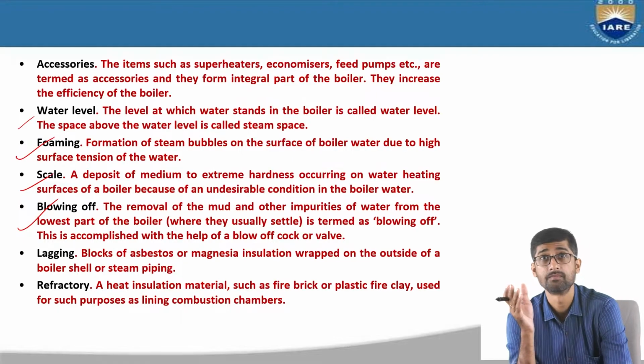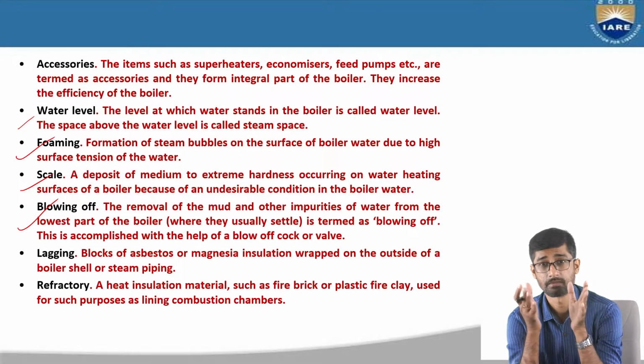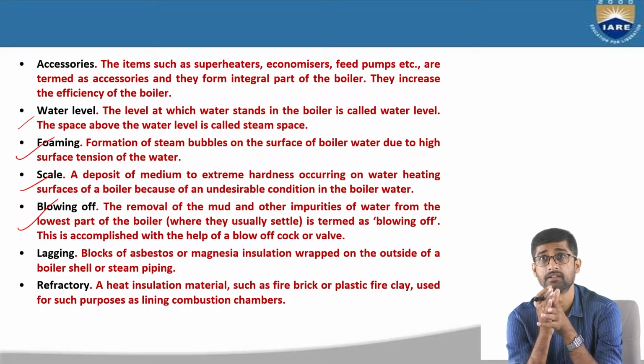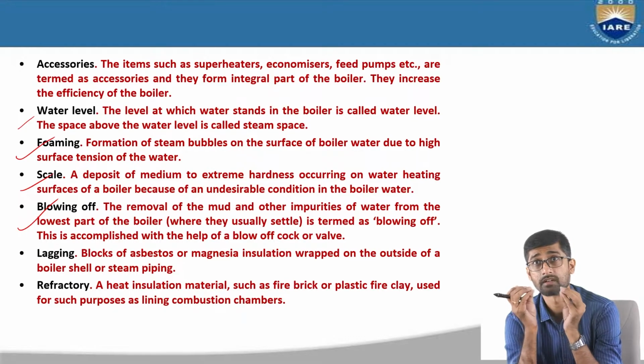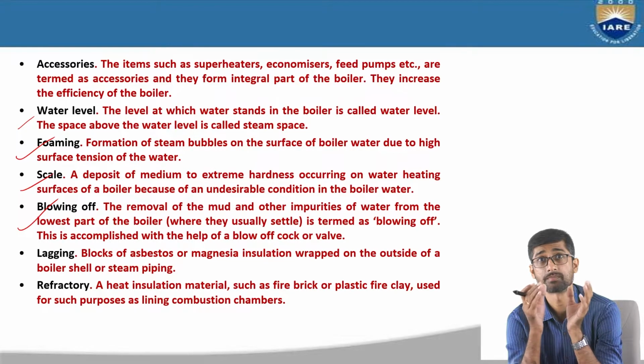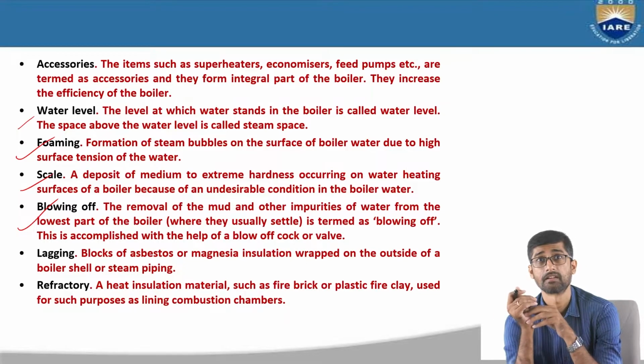Next one is blowing off. It is the removal of mud and other impurities. After burning of fuel, there is some ash, which is an unnecessary part. So removing that unnecessary part from the water at the lower part of the boiler is termed blowing off, and this is accomplished with the help of a blow off cock or blow off valve. Lagging.